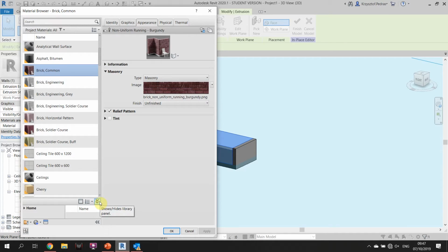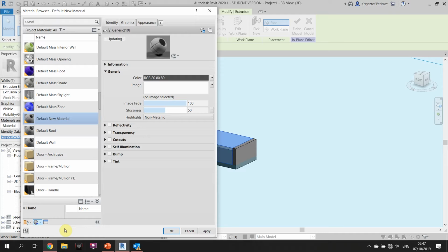So you're gonna have an option in the lower corner of that asset window, a little sphere with a plus. If you click on it, you have an option to create a new material. Okay, so we create a new material. You can see a new material shows up with a default name and a lot of options to choose from.